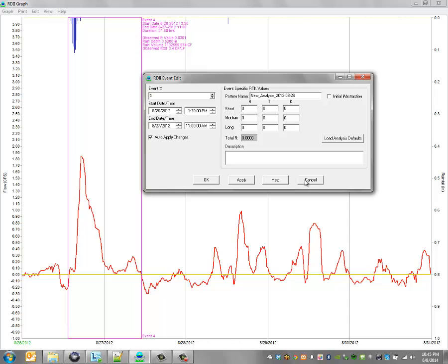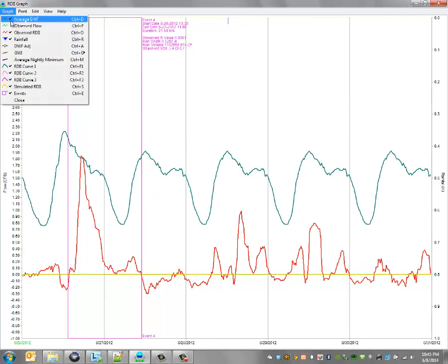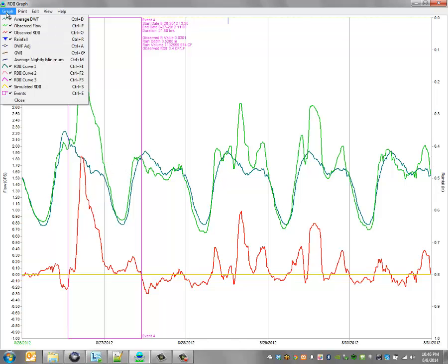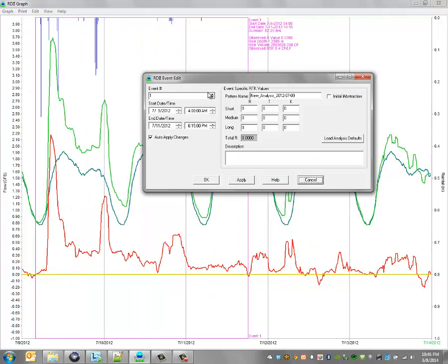Well, in fact, let me just go ahead and show you that. Let me add that back in. So you can see here, the green is what we actually see. And through the magic of SSOAP, we've pulled out the actual diurnal pattern. So even though it didn't occur because it was raining, we pulled that out. The difference of the two is right here, the red, which you can see here is observed RDII, and we haven't really done any kind of cleaning on that, so in some cases it's negative, which isn't true, but you can see here this volume here is where we think is actually extra volume specifically due to rainfall.